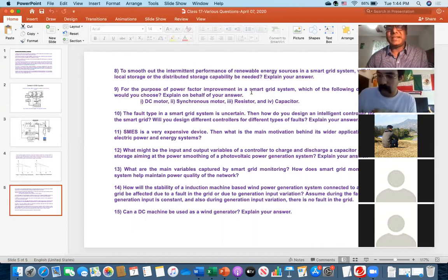When it is in overexcited mode and there is no load in the system, the synchronous motor works perfectly as a capacitor. That's why its name is synchronous condenser. Please everybody write down the name, synchronous condenser. When the motor has no load or very little load and it works in overexcitation mode, or in the leading power factor mode, it behaves perfectly as a capacitor.